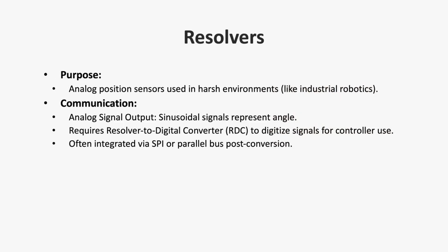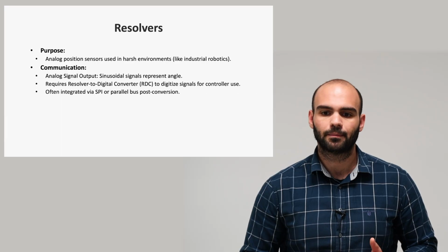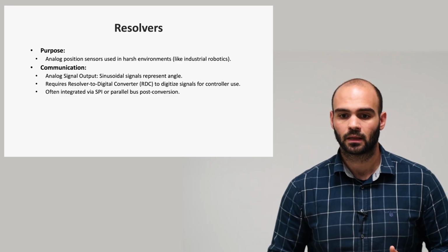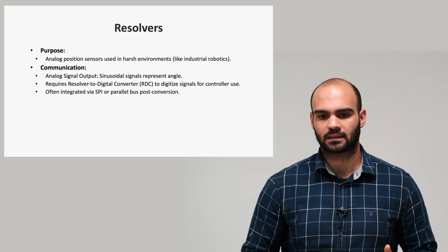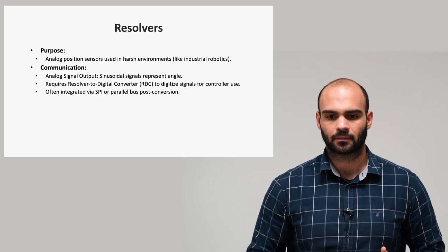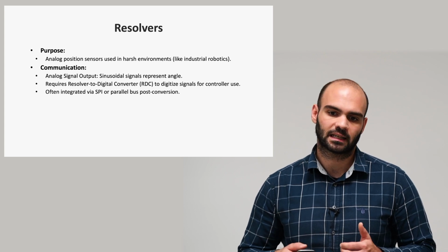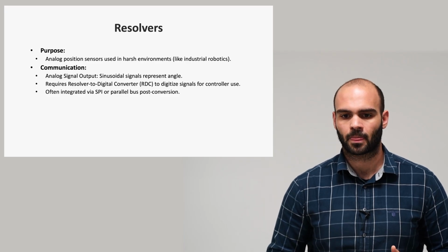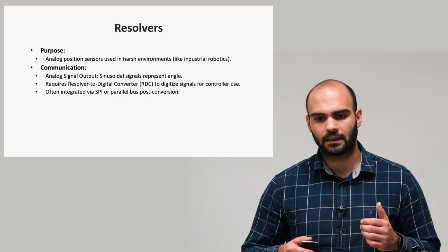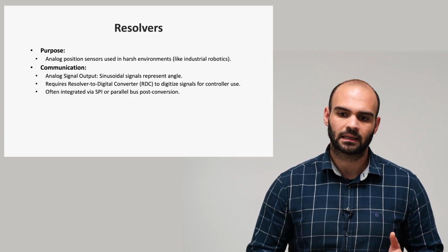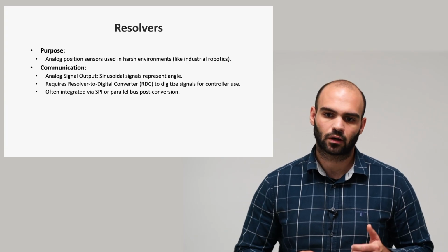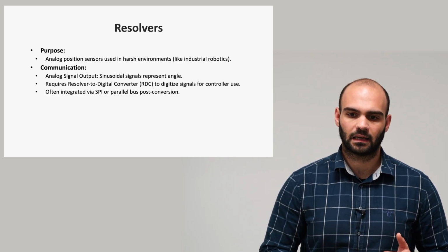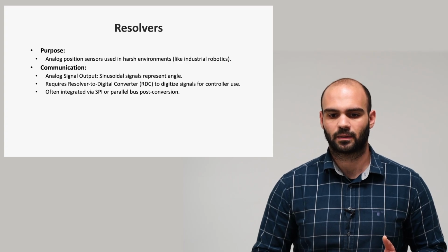Resolvers are analog position sensors that are highly valued in industrial robotics because they perform reliably in harsh environments like high temperatures, dust, or vibrations. They work by generating sinusoidal signals that represent the angular position of a shaft. However, since modern controllers use digital signals, a resolver-to-digital converter, or RDC, is required to translate this data. Once converted, the signals can be integrated through communication methods such as SPI or parallel buses. Resolvers are often chosen when durability and reliability matter more than resolution, making them ideal for heavy-duty robotic systems in factories or aerospace.